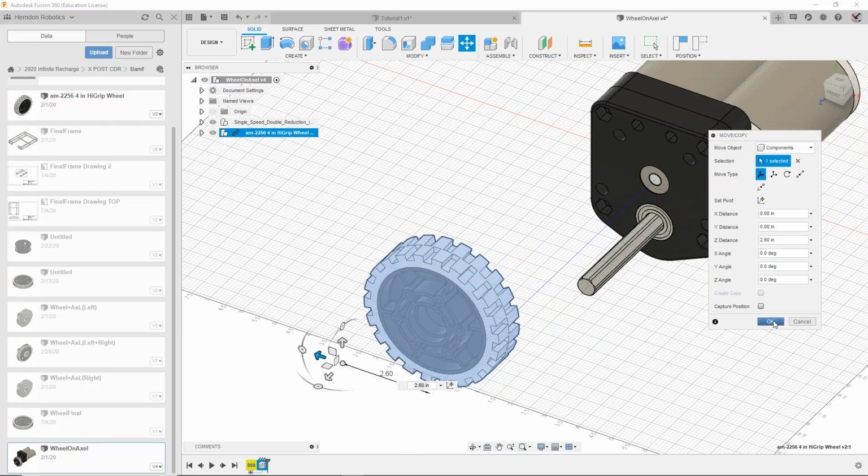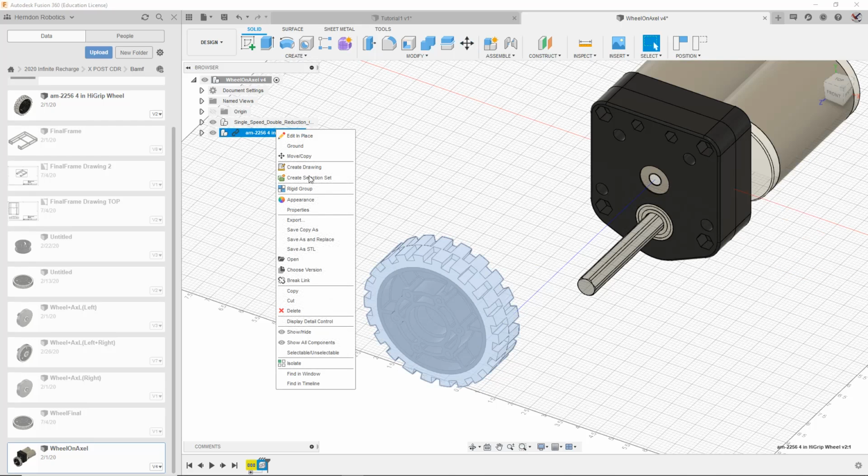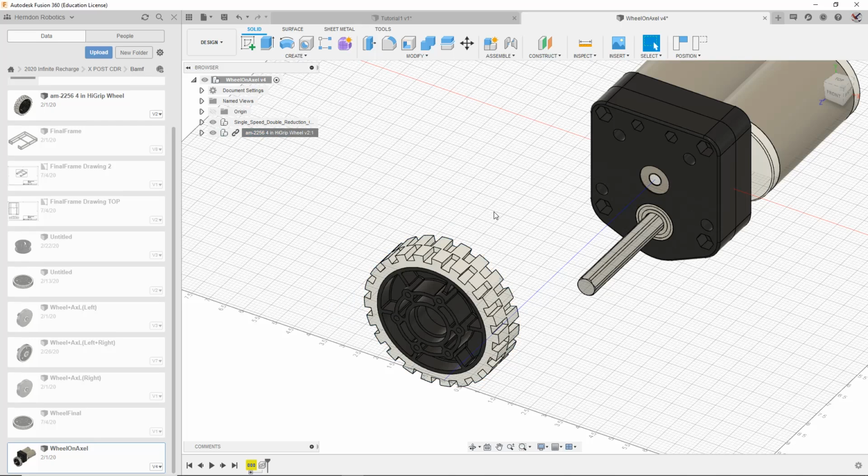So what I do is I click on this, and then you can hit rigid group, which basically makes it so the entire thing won't move. It'll be firm. So what joints do is basically a connecting point. So two pieces get held together. This would be the case if the wheel's on the axle, but in the model, the screws don't really mean anything. So this is how you'd make them do things. Or if you have a ball and a socket, something similar.